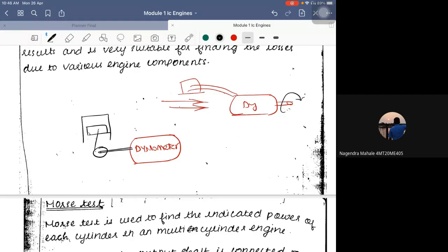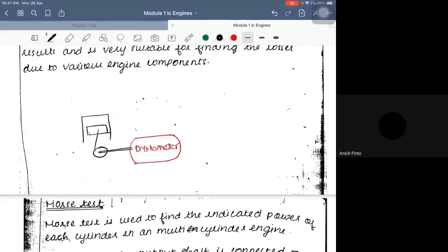Got the concept, everyone, about the dynamometer? Correct? So either way is possible. If we give the shaft power input, electricity would be produced. On the other hand, if you give electricity, shaft power output would be produced. So that is the funda. Now what I'll be doing is operating my engine with certain loading conditions. Say I give 50% of the fuel and 50% of the load, and I maintain speed constant. Then I would just run this particular dynamometer.